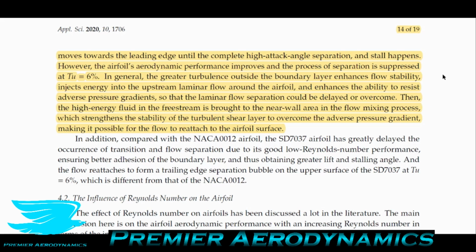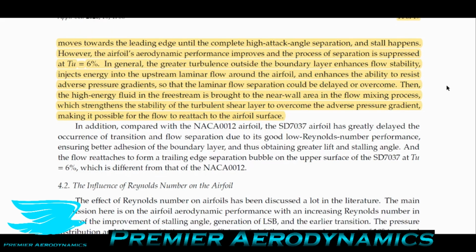So turbulence breaks down three-dimensionally. There's a law that says even if you have two-dimensional turbulence, that will break down three-dimensionally. So even if you don't have any disturbances in one direction, the breakdown of features and the transition to turbulence will then create a three-dimensional effect and drag fluid from other regions. And that's what's happening here. So that's very cool.